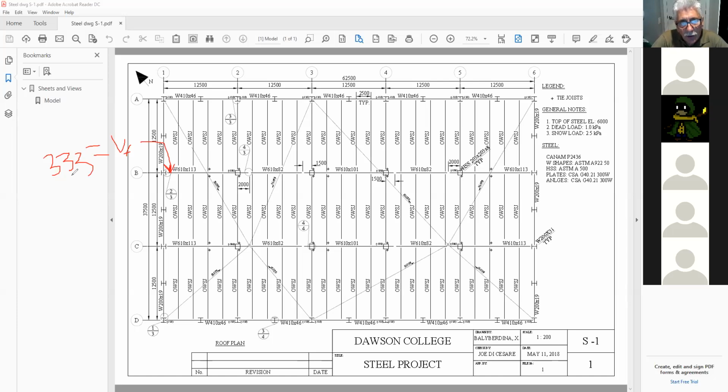Now, like a lot of structural steel drawings, when they have these non-simply supported members that you can't get the load from the beam tables, the structural engineer will always give you the force near the column for what you have to design the connection for. And that's a good structural drawing. If he doesn't, he's going to get bothered because he's going to get called up by the guy that's designed the connection, and he's going to ask for the information.